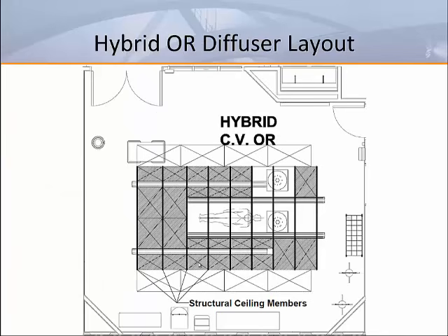The ceiling mounted equipment in this example is suspended from structural members that are integrated into the monolithic ceiling or integrated ceiling system. The location and spacing of these members, as specified by the imaging manufacturers, will typically prevent the use of standard size diffusers offered by HVAC manufacturers. Early coordination with HVAC equipment manufacturers will allow custom size unidirectional diffusers to be designed. Here, you can see the custom size diffusers highlighted in the shaded portions of the array.